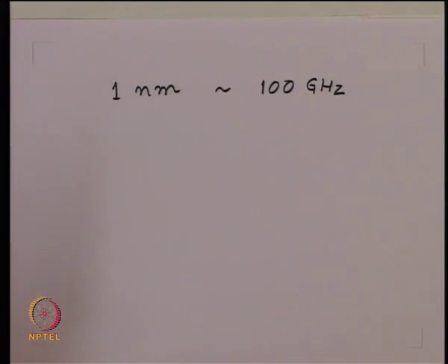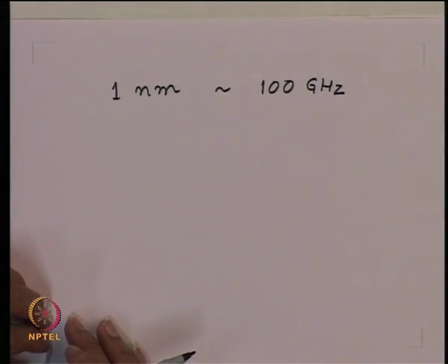So, if I have an optical carrier whose spectral width is 1 nanometer, then this carrier, if I look at it on the spectrum analyzer, will not look like a delta function, it will look like a distributed spectrum with a frequency range effectively of the order of about 100 gigahertz.